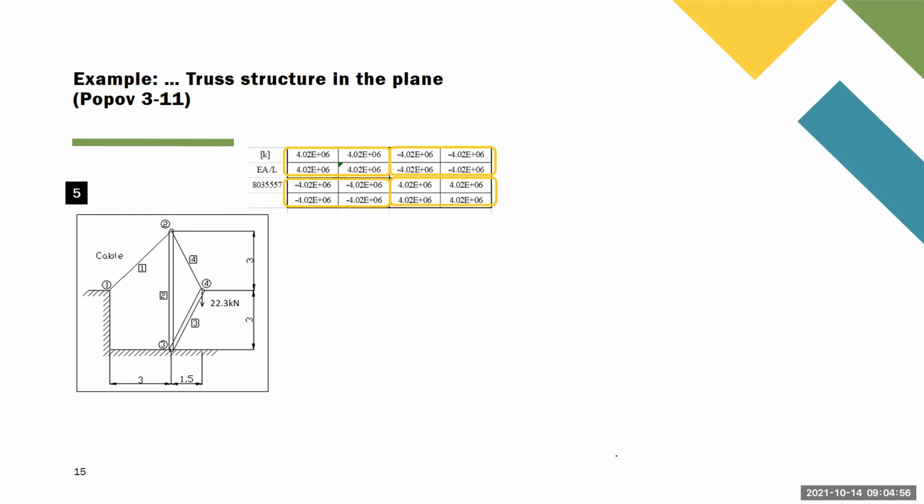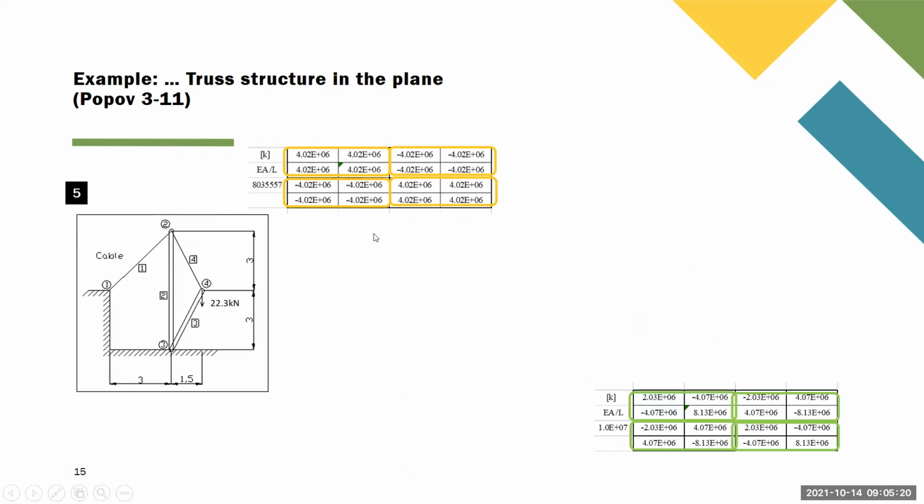So what we do is we split each one of these matrices in 4 pieces. This is multiplied by the first joint and produces forces in the first joint. This is multiplication of the second joint and produces the contribution for the first joint. Similarly for the second forces. Okay, now this is the first element. This is the fourth element.